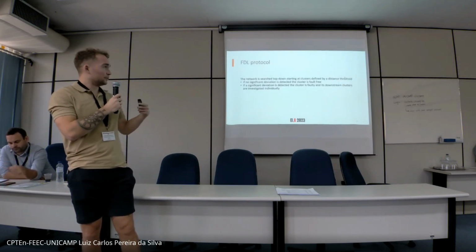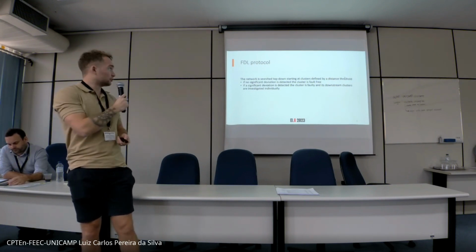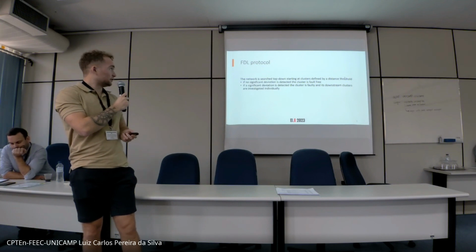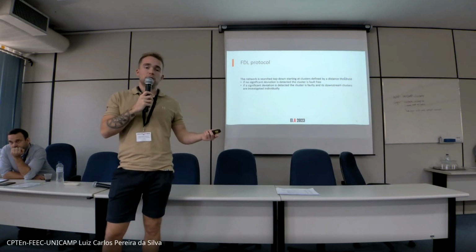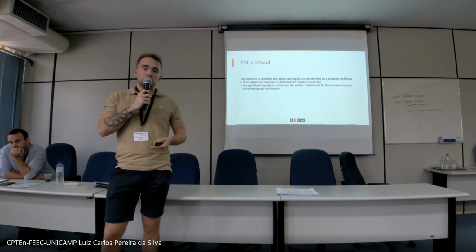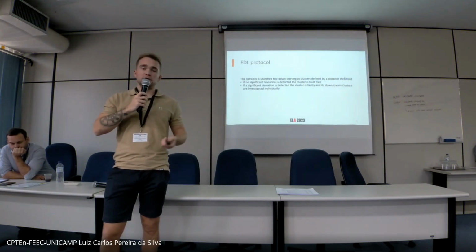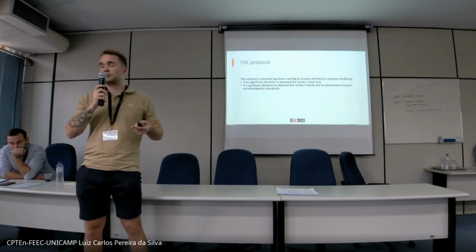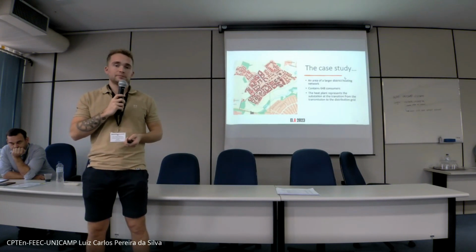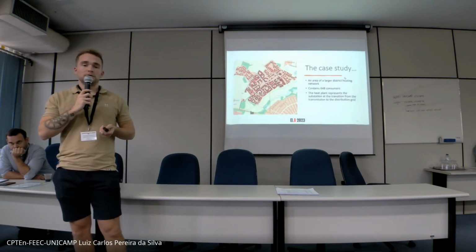We would start with one cluster, potentially consisting of multiple subclusters downstream. If we detect a significant deviation between the simulated flow and the virtual flow meter... if we don't detect a significant deviation, then the clusters fall free. We move on. If we do detect a significant deviation, then the cluster is faulty and its downstream clusters are investigated individually.